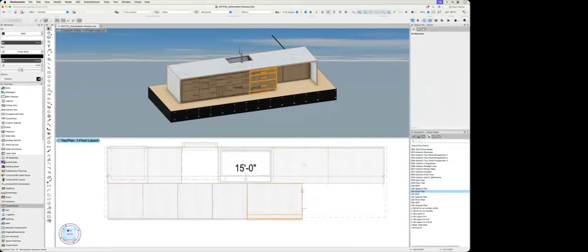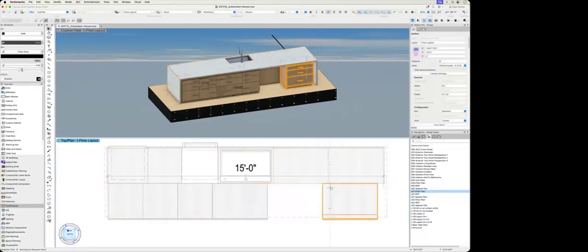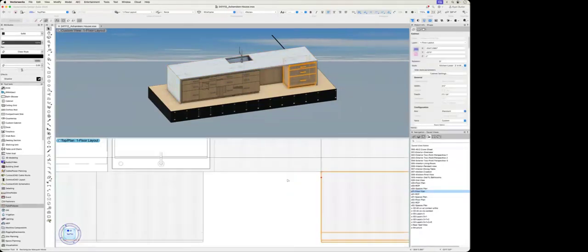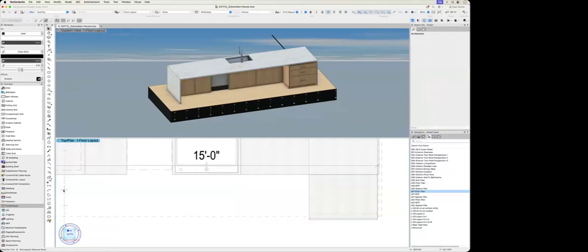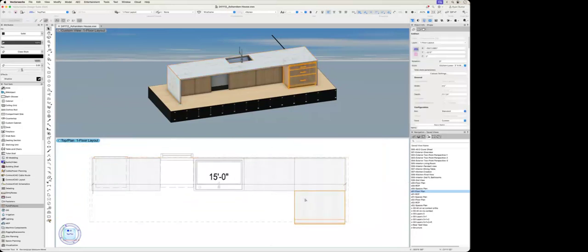And now we will adjust these accordingly. And since these cabinets are all the same width, we can just duplicate them by using the Move by Points tool. So I can move and duplicate at the same time if I press Shift M. That tool is also in the basic tool palette. And if I have the second mode enabled, I can do a number of duplicates, and I could do, let's do 4. And then I will duplicate.